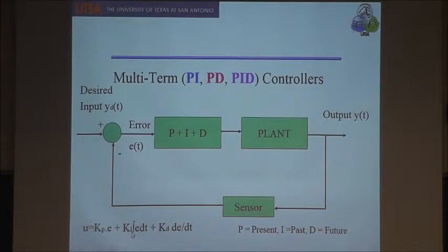As you can see, because of that integration operation, whatever the number of so-called state variables in the plant, this integral adds one to it. If you have only one input, it adds one; if you have more than one input, you add that many variables to the plant. It becomes a bit more complicated because of that, but not too complicated.